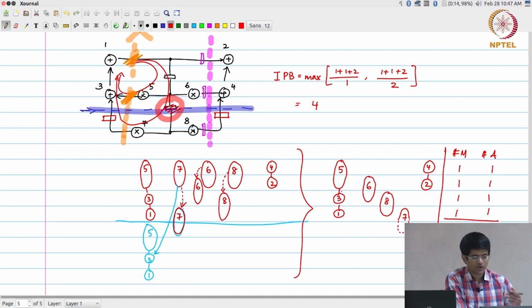Okay, and what we saw was, let's look at the possible places where I can do pipelining and retiming, and we were able to identify fairly easily in this case 2 places where I could do the pipelining and the retiming such that the dependencies were broken. Now after that, what we did was still a little bit of looking at it and trial and error, saying, okay, if I do it this way, then I can move this around, etc. There are procedures that can do this in a more systematic fashion, right? And that's what the entire study of scheduling techniques is about.